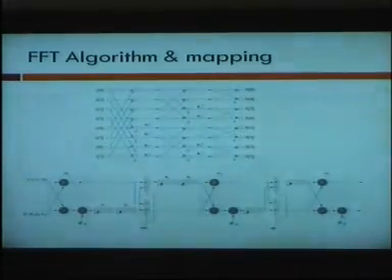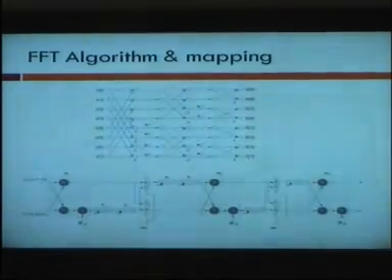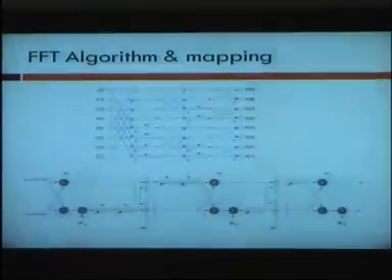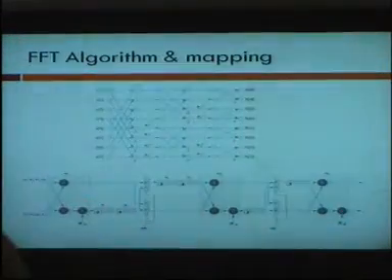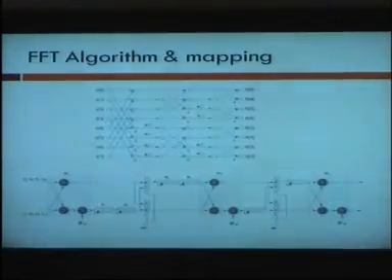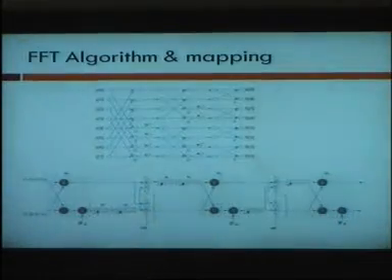By 12 times means there will be only one butterfly. So one butterfly, you use it 12 times to do your FFT. You can fold it by 6, by 2, by 3, by 4. So that's where the challenges are in the design, knowing how much folding you need to do of an algorithm, that is quite challenging.